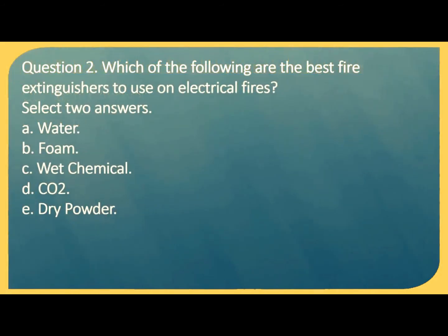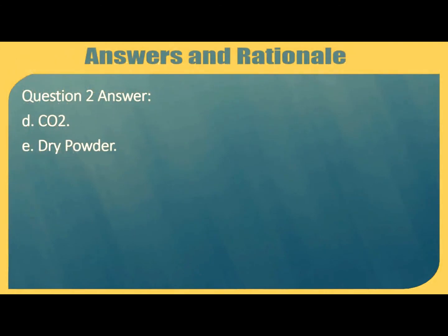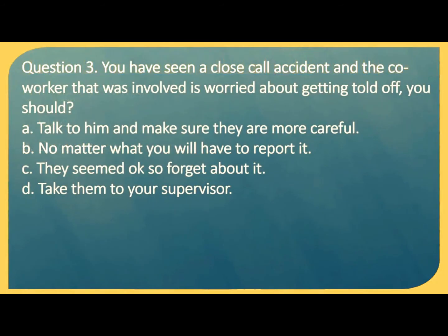Question 2. Which of the following are the best fire extinguishers to use on electrical fires? Select 2 answers. A. Water. B. Foam. C. Wet chemical. D. CO2. E. Dry powder. Question 2. Answer: D. CO2. E. Dry powder.